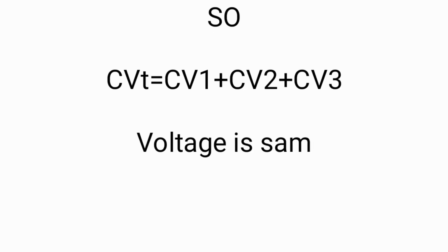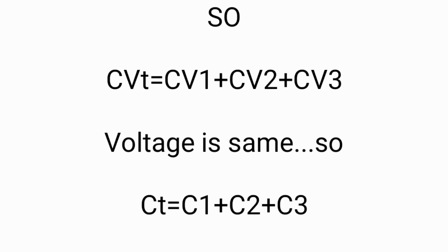Therefore, as the voltage V is common for parallel connected capacitors, we can divide both sides of the above equation through by the voltage, leaving just the capacitance, and by simply adding together the values of the individual capacitances we get the total capacitance CT. Also, this equation is not dependent upon the number of capacitors in parallel in the branch, and can therefore be generalized for any number n of parallel capacitors connected together.